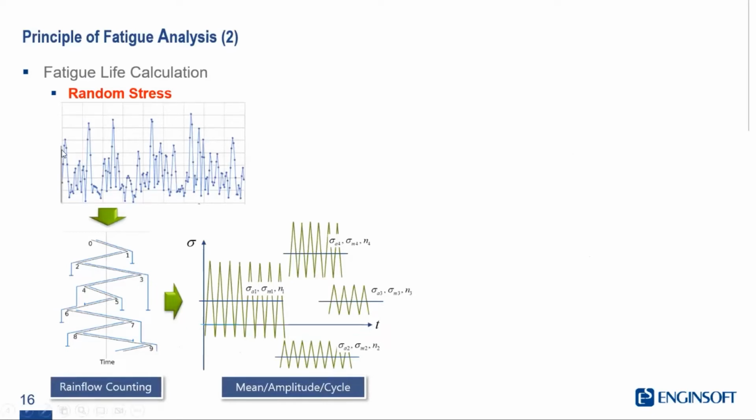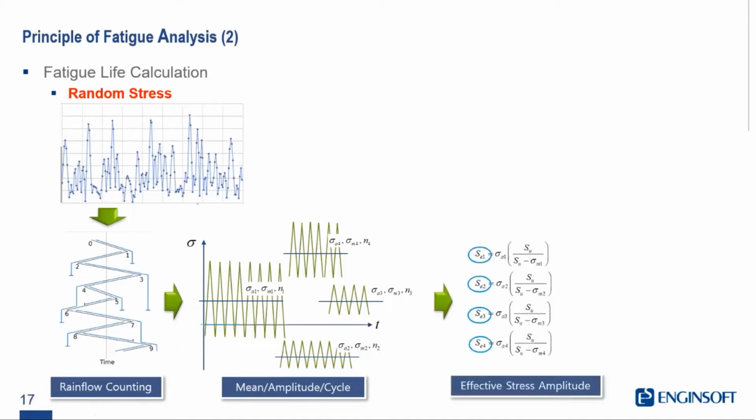And basically, what we're doing is taking a subset of this, turning it on its side, and then saying, okay, we're going to count every time that we change direction. When you actually draw it out, it looks like rain falling off of a water feature, basically. By looking at each one of these individual components, you can break down a very complicated problem into a bunch of really small problems, solve those, and then bind them back together at the end.